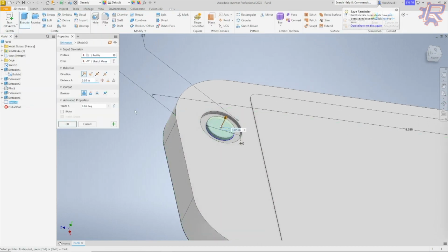And since this is going to be our Joy-Con, let's make it not straight up. And what I mean by that is once we extrude it to 0.2, we can change the angle of this extrude, change the taper. And that's in these advanced properties. We can make this into -20 to make it going inwards. If you make it a positive angle, it's going to go outwards.